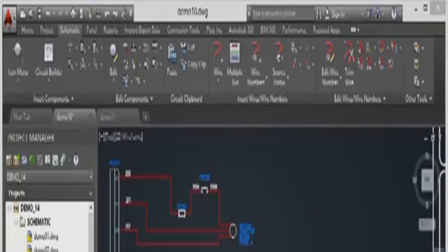If I want to move a circuit around in my AutoCAD Electrical drawing, there's a really neat tool that I can use that allows me to move a circuit but also make sure that all the tags and the wire numbers are up to speed as well. Now, we're staying in the Demo 14 project. We're still in the Demo 10 drawing at the moment.